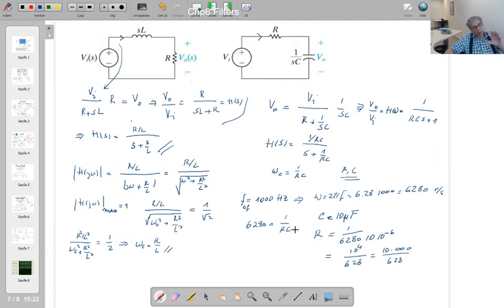So among many of these pairs, you can choose the best one, the optimum pair, as the R and C value calculation. If you choose these element values, you end up with a filter whose cutoff frequency is 1000 Hertz, or 1 kilohertz.